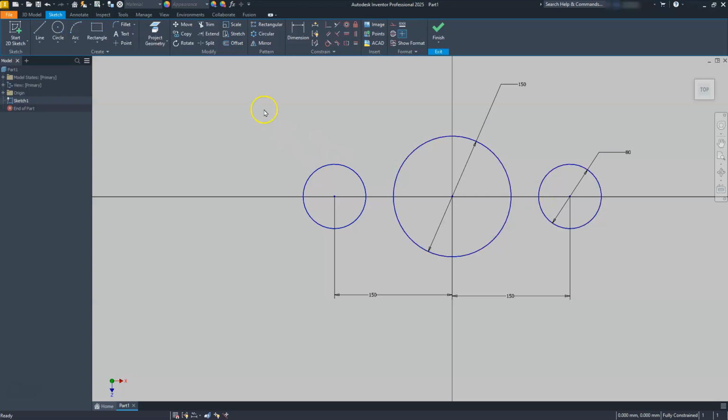Right? So I would love to be able to go, hey, I want to put a fillet here. So can I use the fillet command and then tell it that I have a radius of 100 and then select here and here, right? You can see that it won't even let me select these circles. So we have to create these the old way. We have to draw a circle here, and it has a radius of 100. So I'm just going to create 4 circles here.